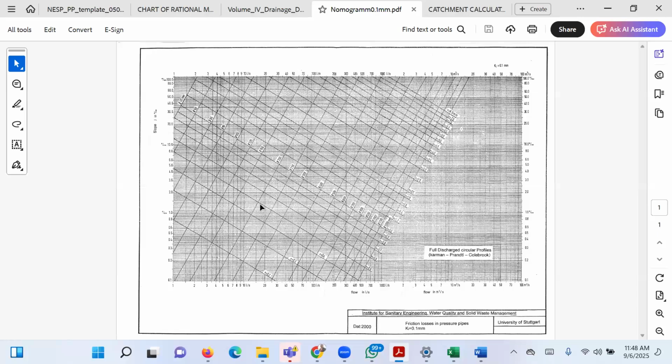It's very possible, sir, that what you need to do as a designer is play around with the slope. It could simply mean you dig more. Flat lands can be quite difficult. The implication is that the minimum flow velocity in a sewer network is 0.5 meters per second. The complaint they are making is blockage.